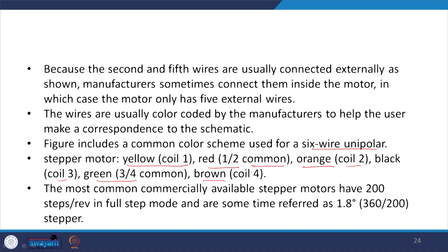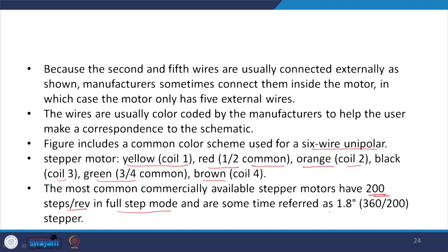Most commercially available stepper motors have 200 steps per revolution in the full step mode, and are sometimes referred to as 1.8 degree steppers, that is 360 divided by 200.